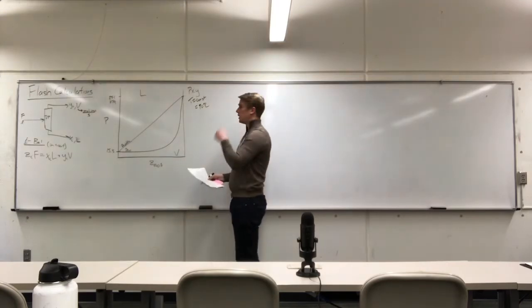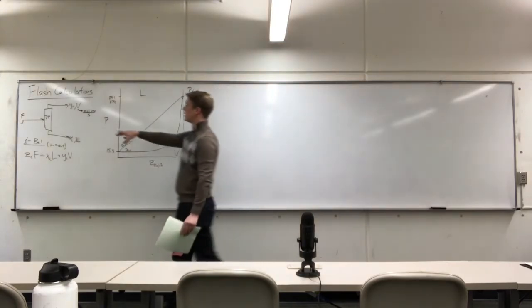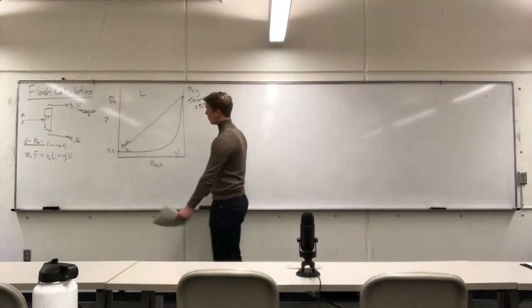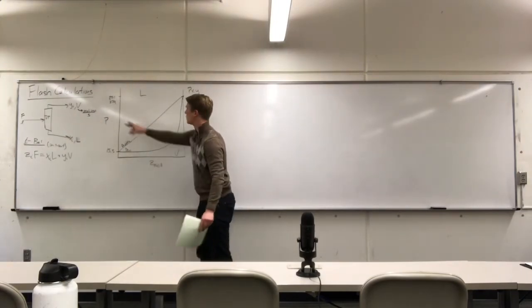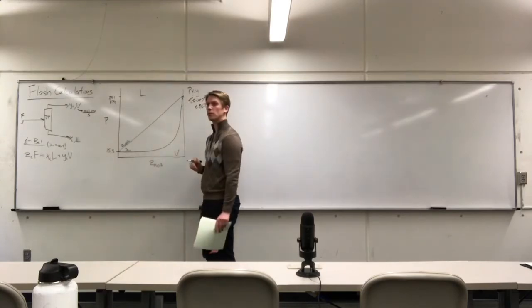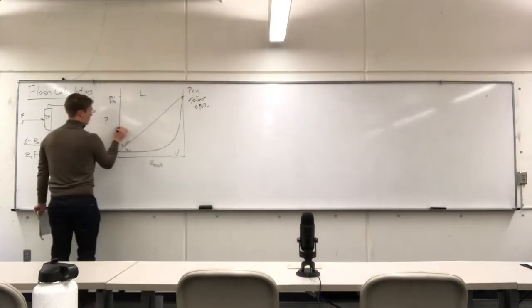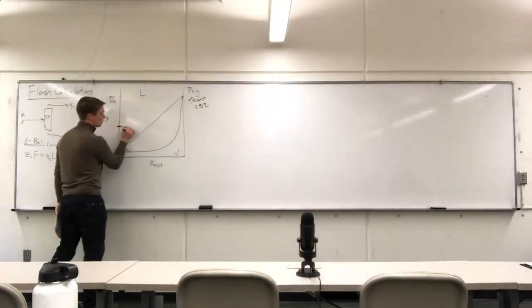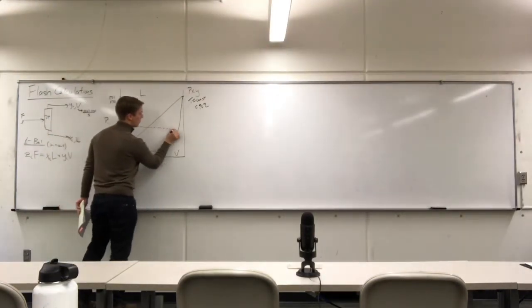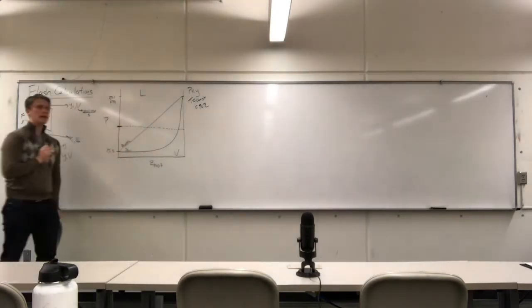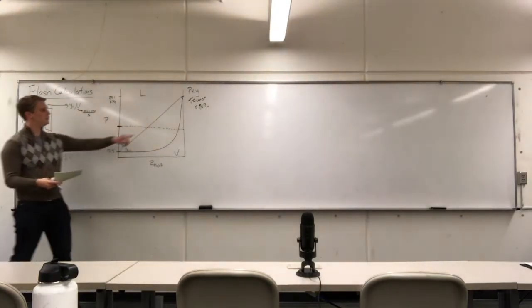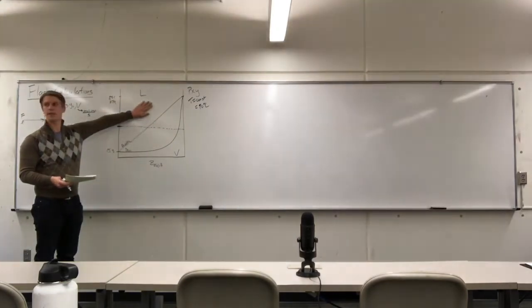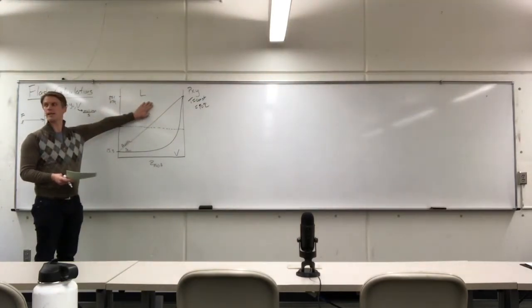In a flash calculation, what you may see in a homework problem is I will say that you have some composition at some pressure and at some temperature. So for example, let's just say this is our system pressure right here. Now I can draw a horizontal line. Now this line is a line of constant pressure. This diagram is a plane of constant temperature.